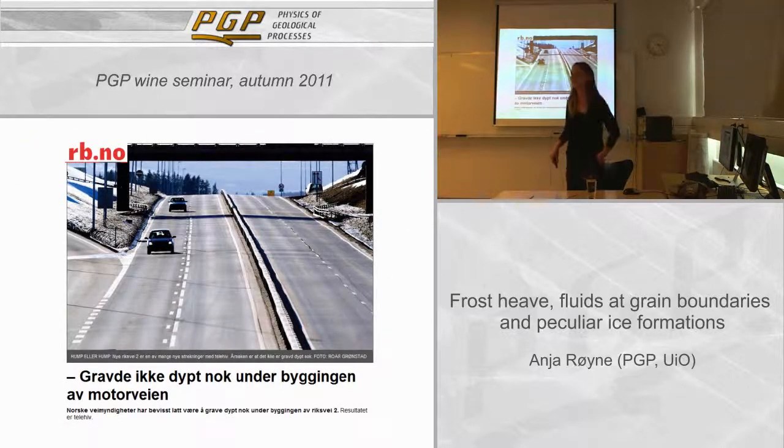So, motivation. Every year, and especially last year, I guess it was because they had just finished some very big highway projects in Norway, and then we had a cold winter, and after the winter the roads looked like this. It said they did not dig deep enough when they built the highway. When you build a highway, you have to dig deep enough and fill in coarse material to avoid frost heave.